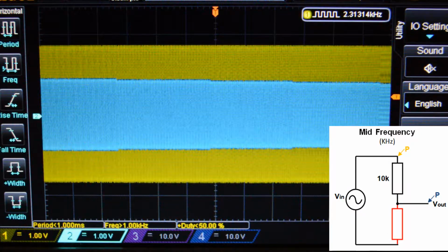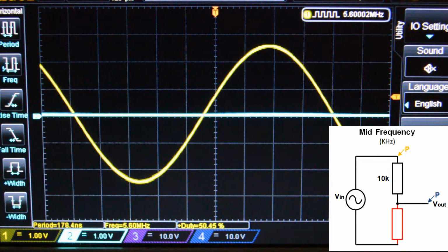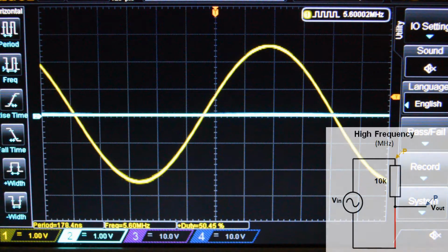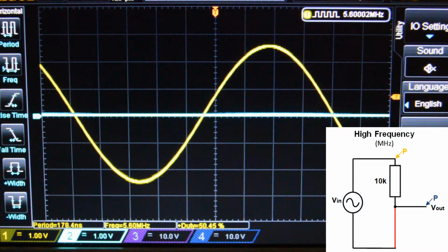This resistive quality in the capacitor that is dependent on frequency is known as reactance. The higher the frequency, the less reactive it becomes. When we get into the megahertz, the capacitor is almost acting like a short circuit due to its reactance being very small, where the output is almost being shorted to ground.